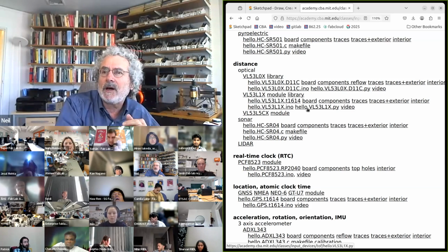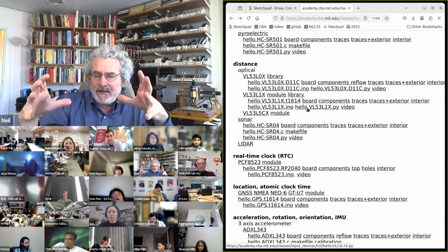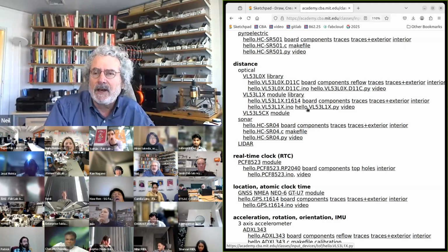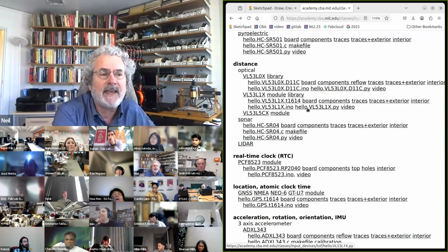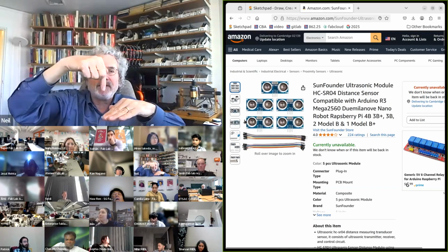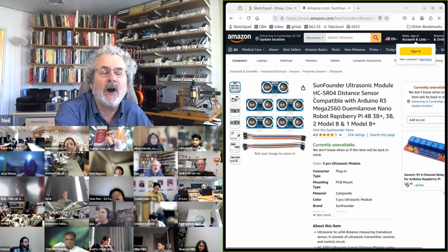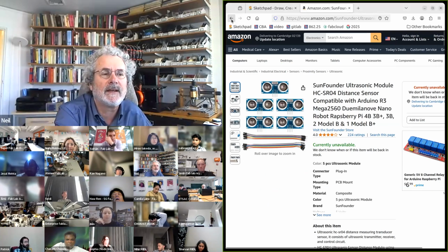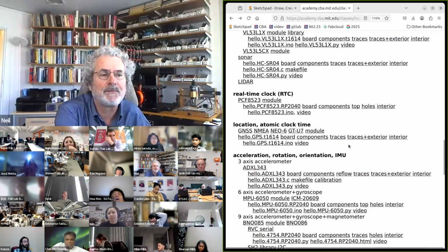Let's see, for water depth, if it's a container, you can put electrodes around. You can do that with the step response. For water depth, that actually is a case where I would do sonar. The laser optical won't have a good reflection from the top of the surface of the water. The ultrasound will have a very clear surface from the top of the water tank. So for a big tank, I would use sonar. For a small one, I would do the step response.